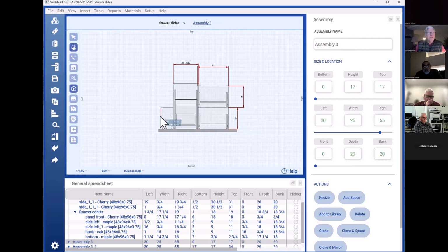You can't go into an assembly. If you want to go point to point, that's this tool right there. And say I wanted to know the total distance between there and there, it's 45 inches, which is maybe a little bit off.